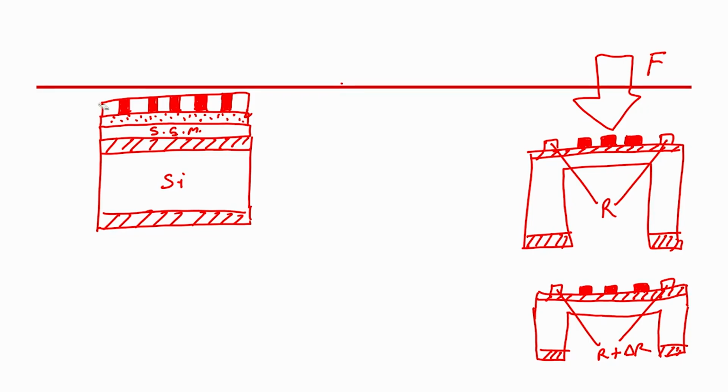So, now let us assume that we have the strain gauge on the oxidized silicon wafer. I will just draw here, this is our strain gauge. I am making this box bold to help you understand that this is the actual sensing layer, and these are two contact pads which are not bold. Otherwise, everything is the same material. You can also use gold contacts for the final contact pads, but that we will discuss later.